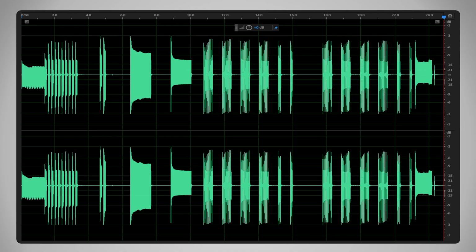You can hear the contact ID handshake first, then the 2300 Hz handshake, and finally, the radio then moves to the 1400 Hz handshake, and the panel then responds with a 4x2 pulse data dump with a kiss-off from the radio at the very end.